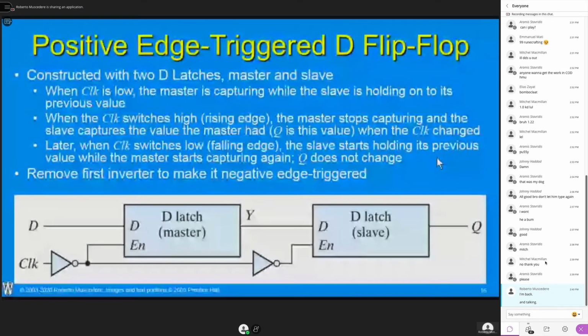And this is certainly something we like for lower power designs where we can just do that. So as long as all of our circuit components are static, in other words, no DRAM, which again, if you guys don't remember, I'll talk about later, you can basically pause the circuit indefinitely. As long as power is applied, it'll work just fine.